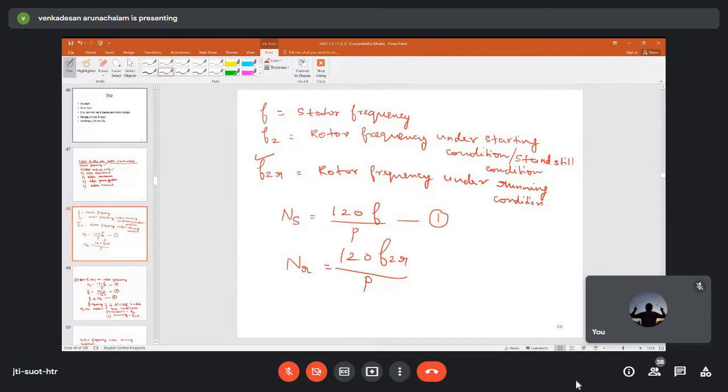The rotor is rotating. The frequency is in the time domain. That is the rate of change. That is because of the relative motion between the stator and the rotor. See, everything, they have not understood from heaven or hell, right? Everything through experiments, they coined all this expression. So this F2R is not simply proportional to NR, it is proportional to NS minus NR. Any doubt in this? Are you understanding this point?